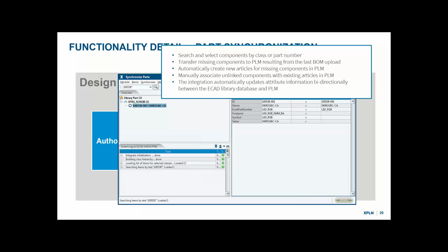Or if you really want to get fancy, you can actually set it up to run from within your PLM workflows. So workflows that have to deal with parts, like a new part introduction, part obsolescence, or part change request, okay? Any of those that may change the status of a part or the metadata on that part would then run the synchronization to ensure anything that changed inside of Windchill was reflected back down into your CAD library.